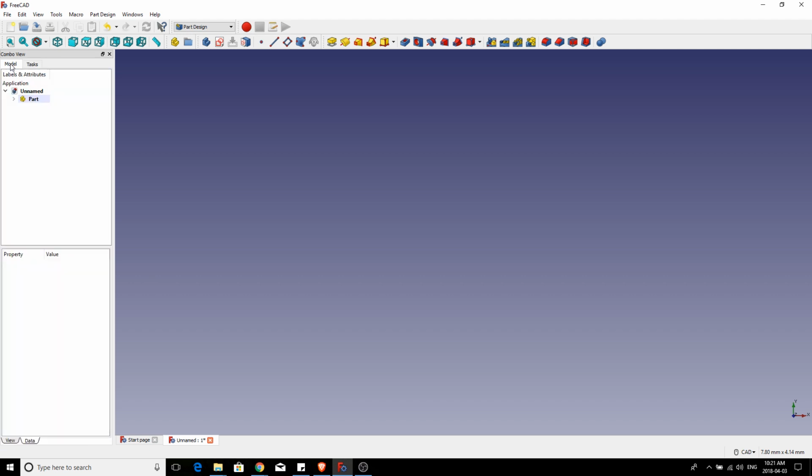If you click on the model, you can see there's the part that we've just created. And inside of it, it's got what's called an origin point. And so this is the starting point for this part we're going to create. Now, the reason why we're doing that is because as your model goes on, you might need more than one part, right? Now, inside of that part, our next move is probably to create a body. So I'm going to click on this create a body right up here, and you'll see from the tooltip that it's going to automatically make that body active, which is great. So I'm going to click on the body.